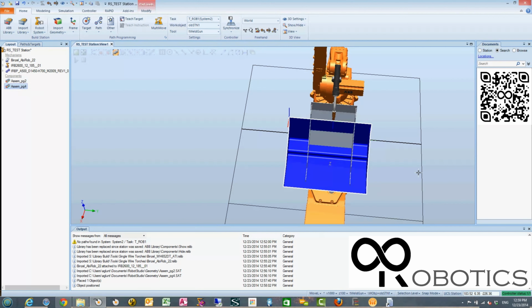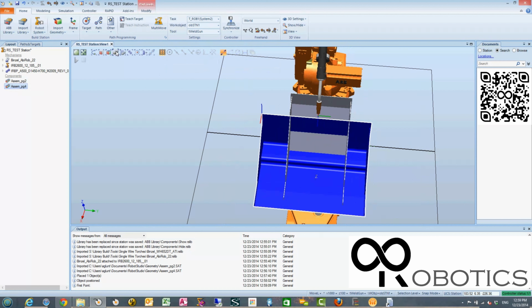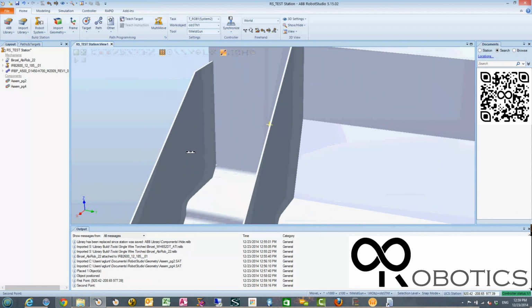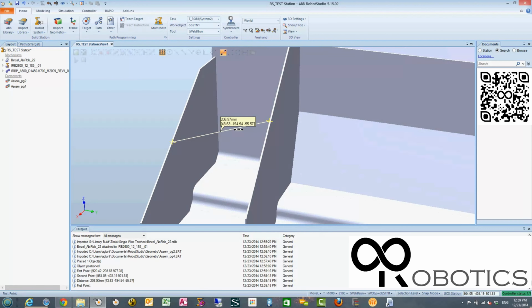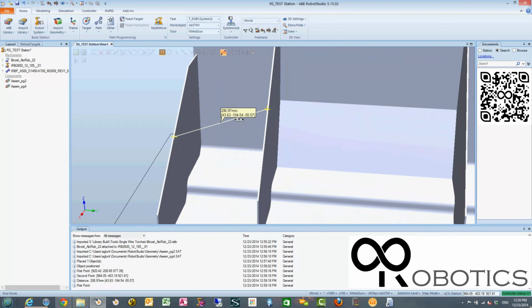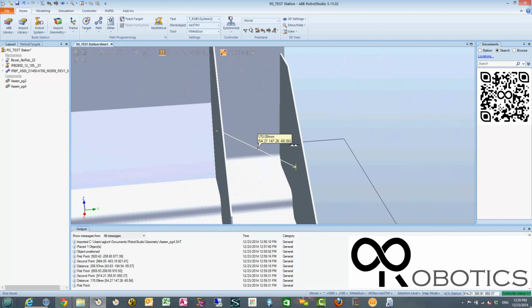Now this part might not be lined up right, so we can go through, here's some measurement tools. We've got a point-to-point measurement, and I can use this snap object. So I can check measurements here and say, hey, from there to there, how far away? And I can check X, Y, or Z. It'll show me each one. So that is, in the Y is what I'm looking at, the Y direction, 194.54, and then I'll go from there to there, 147.